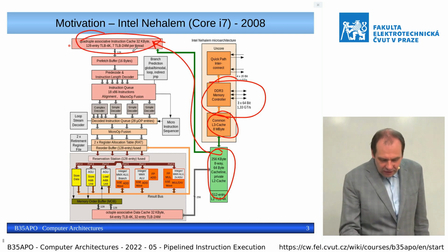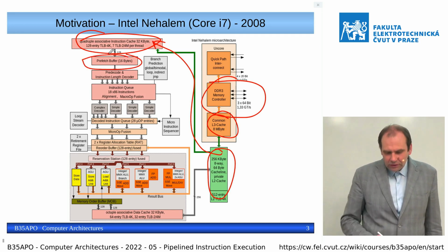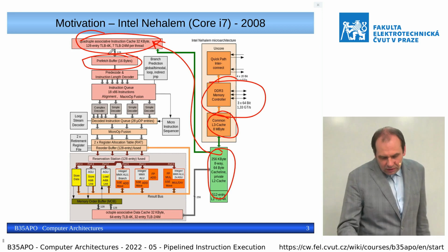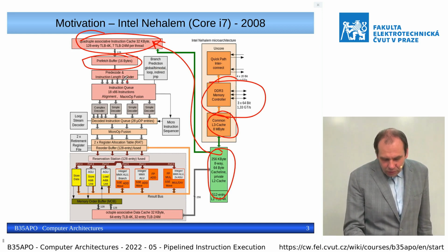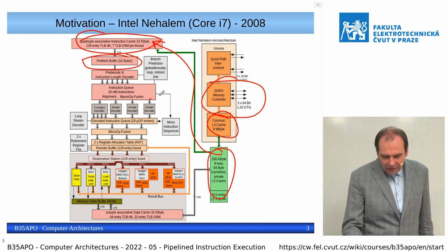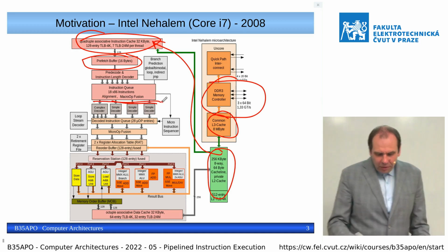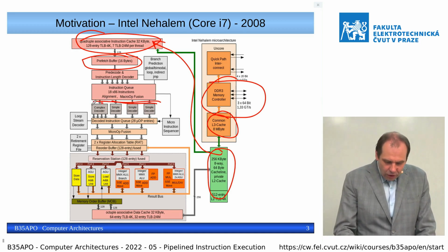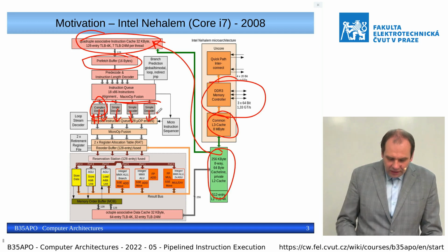Those instructions are fetched on a 16 byte basis, then aligned to match a decoder queue. In this case, we can decode up to 4 instructions, but only one of them can be a complex one which produces multiple RISC-like operations. The other instructions have to be simple.